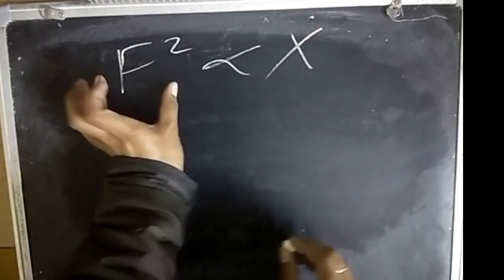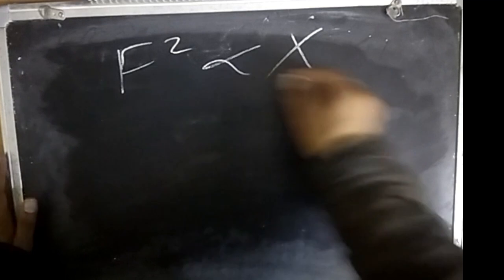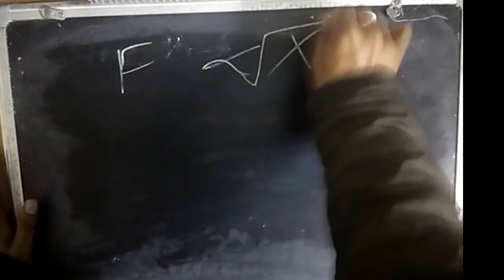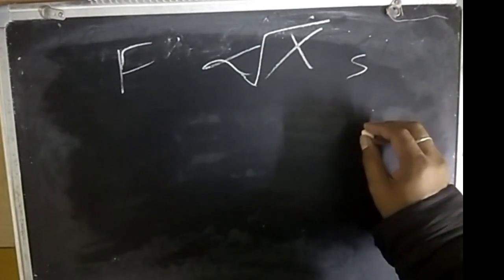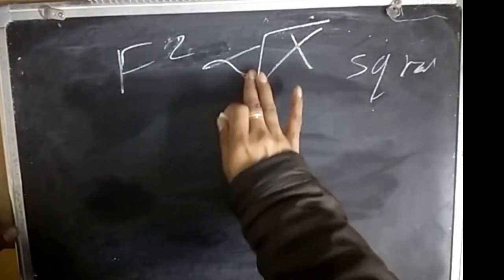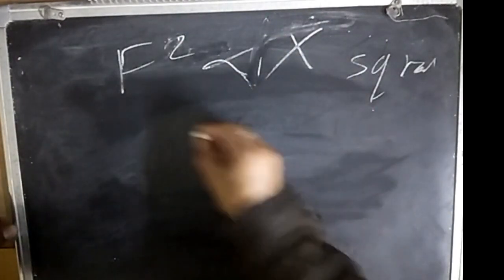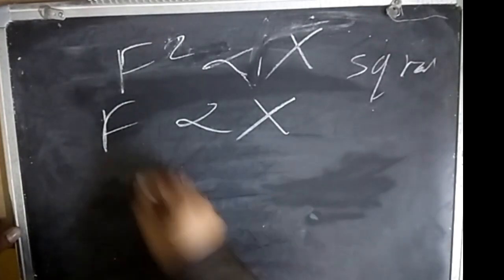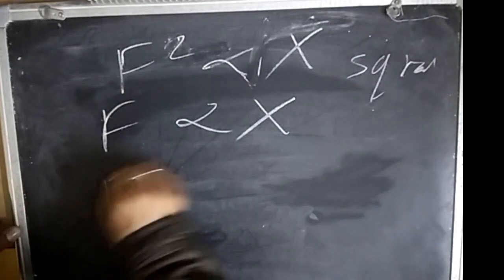This is quick opening because flow is getting squared. Or this would become square root if this goes. So this becomes square root. In that case, that is the same as quick opening. If this becomes F square, that means quick opening. Okay, next is my linear, F, easy. Then there is my equal percentage.